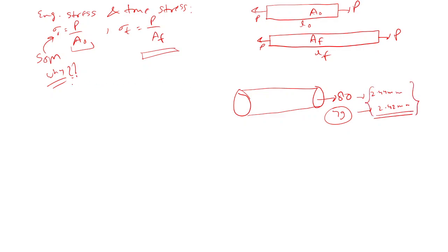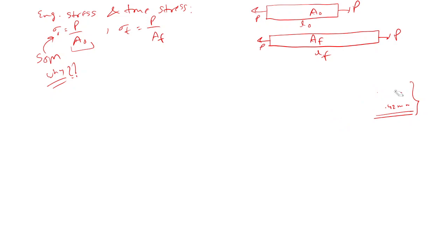So that's why in strength of materials, because our loading condition is usually in the elastic zone, due to the low loading we can use this, and the error in the answer is very comparable to the actual answer. But in the metal cutting and metal forming portion, we will go with true stress only.